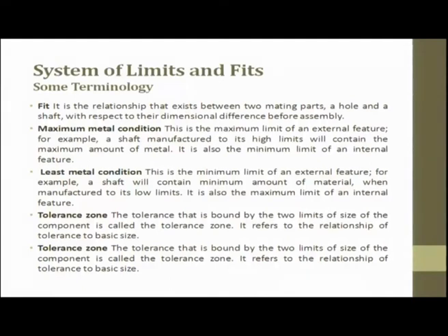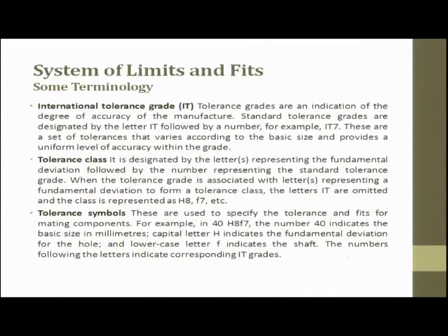Tolerance zone. The zone that is bound by the two limits of size of the component is called the tolerance zone. It refers to the relationship of tolerance to basic size. Then it is the international tolerance grade. Tolerance grades indicate the degree of accuracy of manufacturing. It is used internationally, so that a part can be produced in one place and moved to another. Then tolerance class,